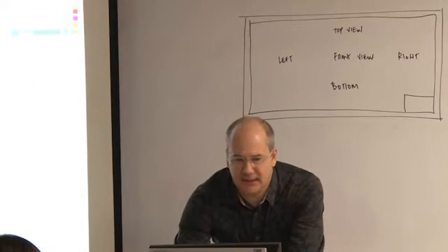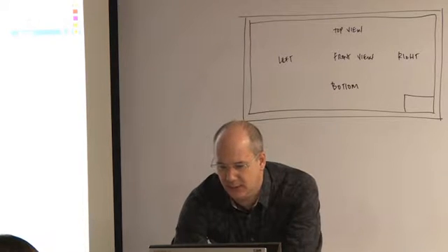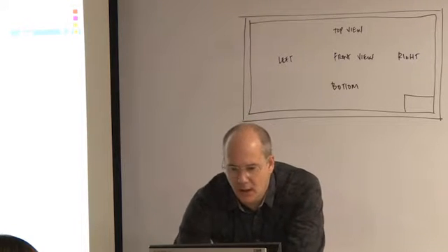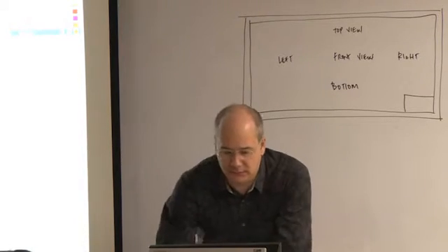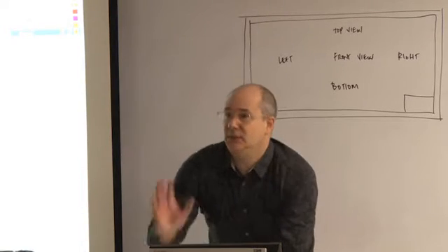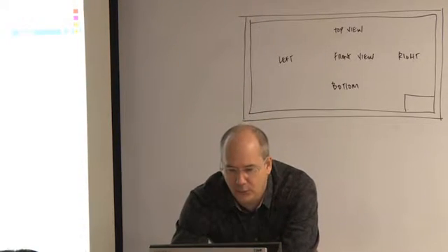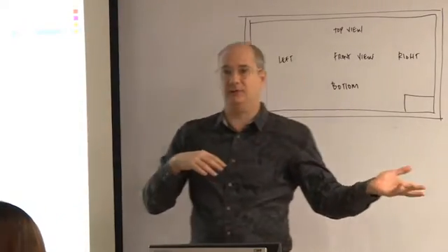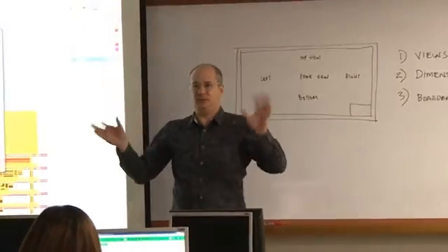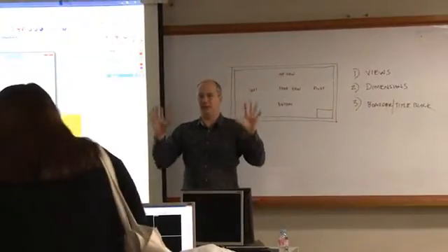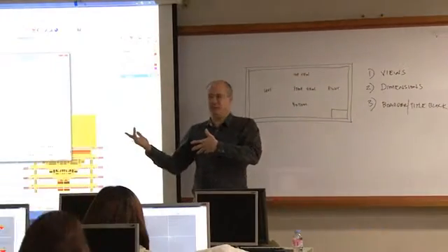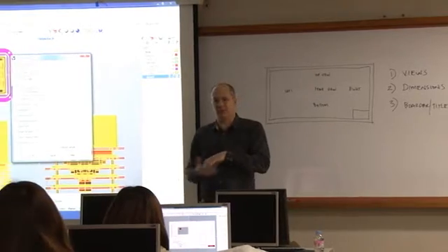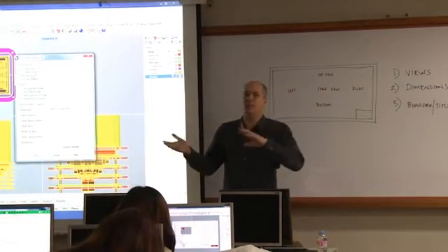Up here it says "select objects to draw." In the perspective view, I pick everything. Enter, and I get my drawing options window. Here, the only thing you need to select is the Four-View USA. They have a USA version and also a European version, because there's a difference between the views in Europe and the USA. Since this software comes from the USA, they come first, and then the European version. But as a designer, you need to know both modes.